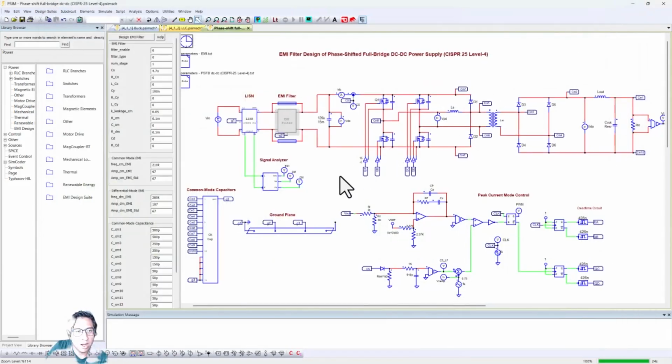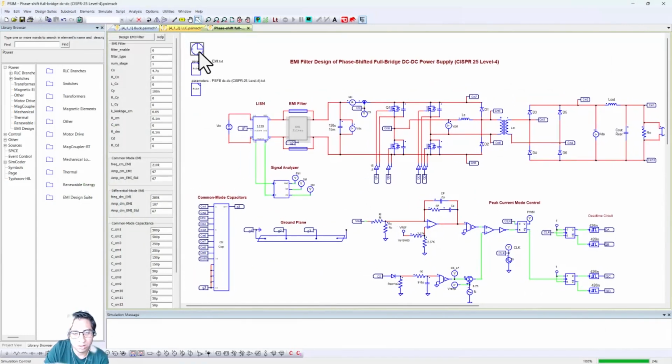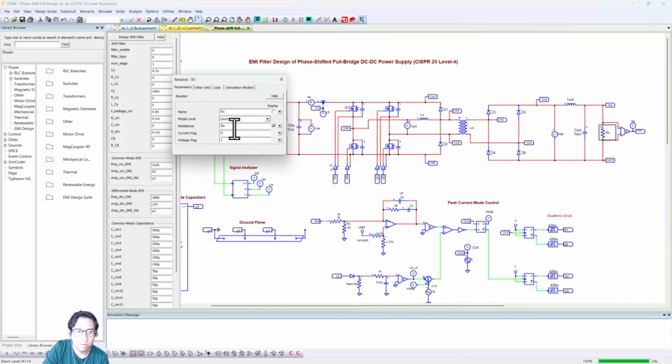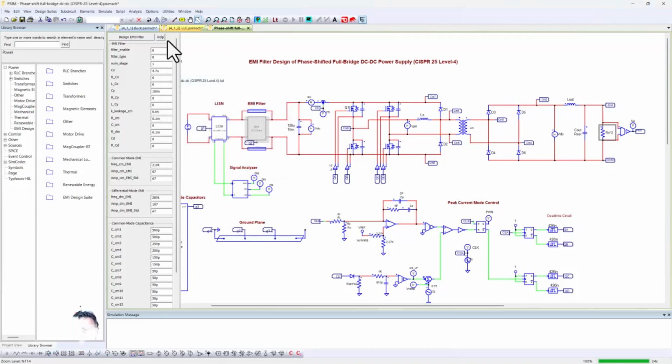Additional things you can do with the load and save flags is to change the passive values of certain components. For instance, if I want to decrease the load, make the resistance be twice its current value, I can do that and the simulation will work. Something that I cannot do is add new components to the simulation, right? So I cannot just place another resistor or another capacitor.